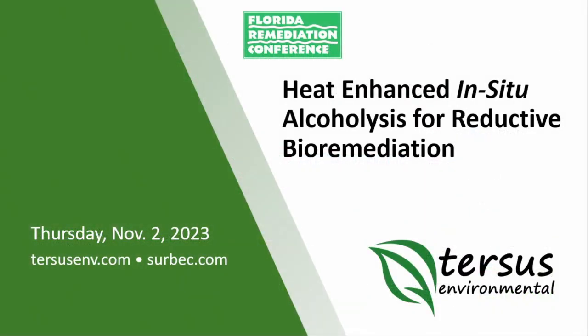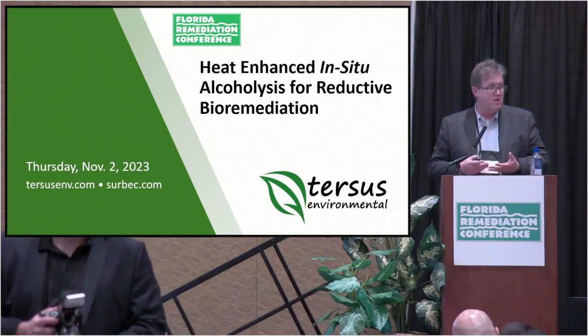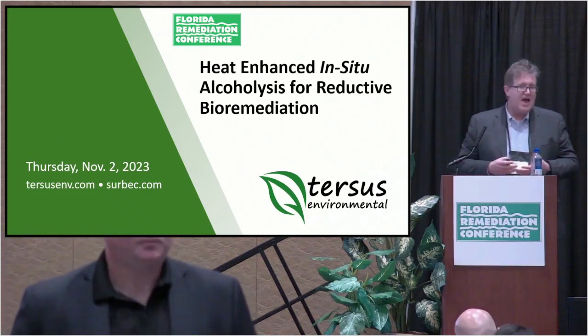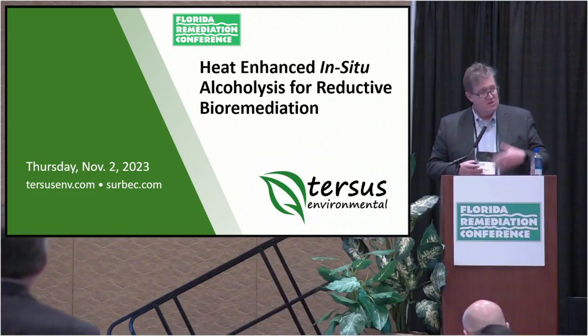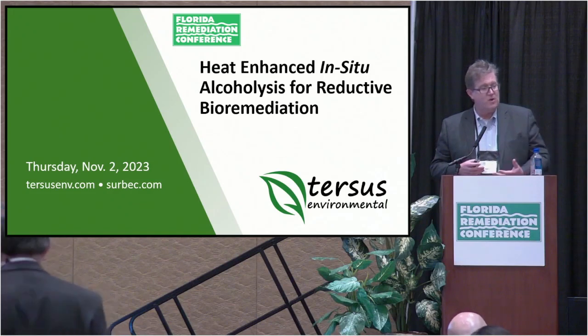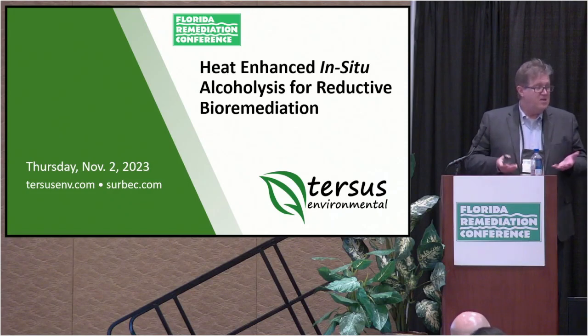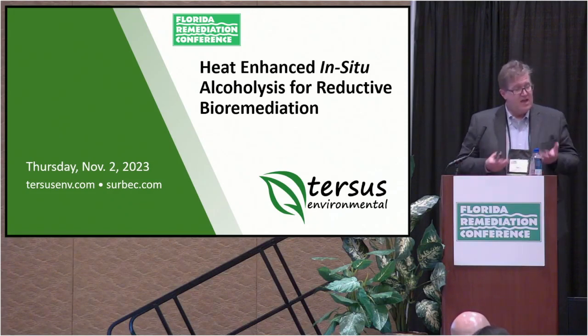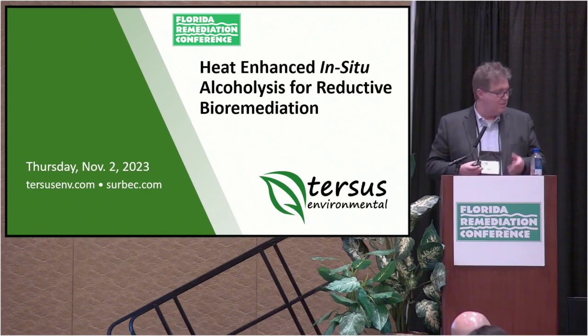Okay, so my talk this afternoon is really on heat-enhanced, catalyzed, reductive bioremediation. What we're doing is adding an electron donor, specifically a vegetable oil, along with an alcohol. We're going to add a catalyst to that, and then additional heat. The purpose of the heat is to increase the yield in this reaction that's going to create volatile fatty acids. And the heat will also help get the temperature to the zone where the Dehalococcoides or Dehalobacter are in their optimal growth temperature range.